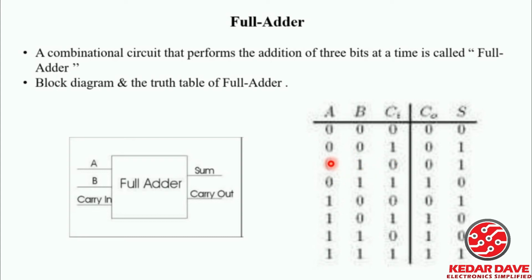So this way, if you check all these terms, then you definitely get some idea about how it differs from the half adder. See over here, 0 plus 1 0 is equal to 0 1. Here what we are doing now, carry is 1 and the other digits are same. 0 1 plus 1 is equal to 1 0, right? 0 plus 1 is nothing but 1, and the output will be 0. See, 1 is there, and 1 plus 1 is 10, right? So 0 will be the sum and 1 will be the carry. So this way it can be represented.